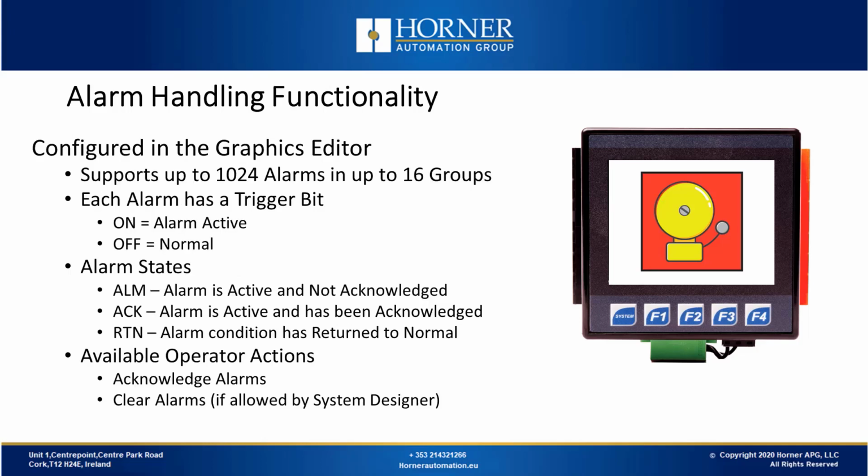Our all-in-one controllers combine the functionality of a PLC and an HMI with built-in I/O and networking. In our Seascape software, alarm handling is configured in the graphics editor. We support up to 1024 alarms and up to 16 groups. Each alarm has a trigger bit. When the trigger bit is on, the alarm is active, and when it's off, the alarm is normal.